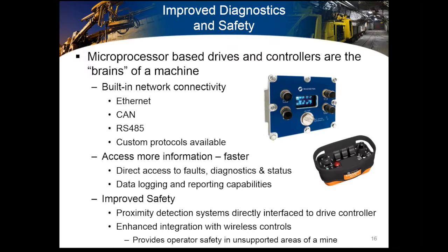This allows for accessing of information within the drive, better diagnostics of the operating parameters of the machine. This directly allows operators to get access to faults, diagnostics, other status, and also allows them to log and report capabilities or issues that might be happening within the inverter and in the operation of the machine.